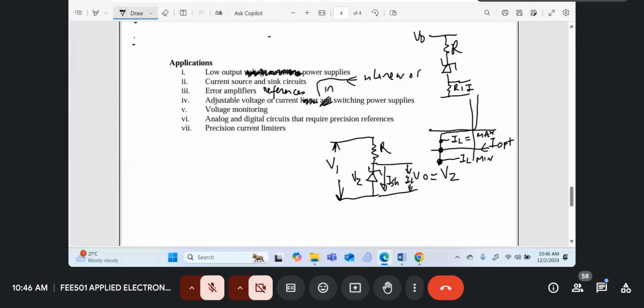So you drop a large voltage. You use a high voltage Zener to drop most of the voltage across the Zener, so that the current passes through the circuit. Let's assume this is a very high voltage, say like 340 volts DC, if you rectify the mains. Then the current I through the circuit will be V0 minus Vz all over capital R plus R1.